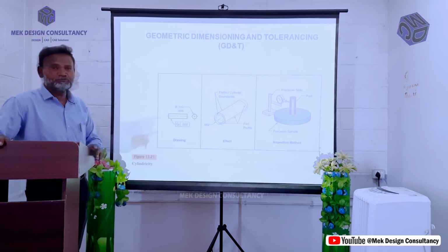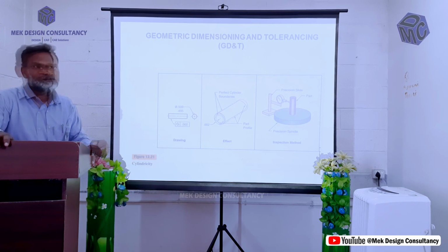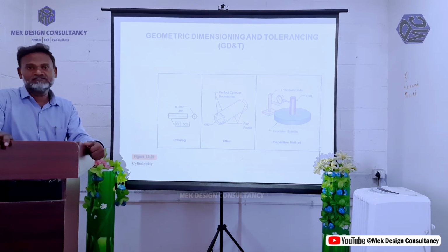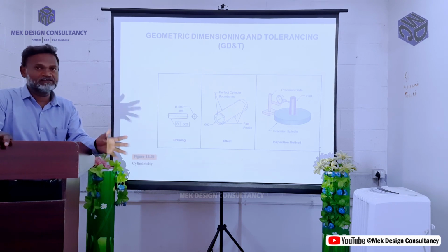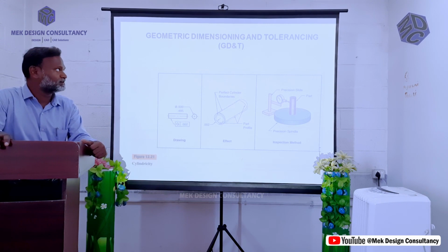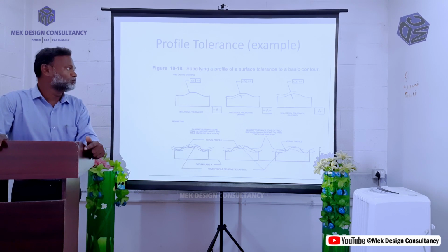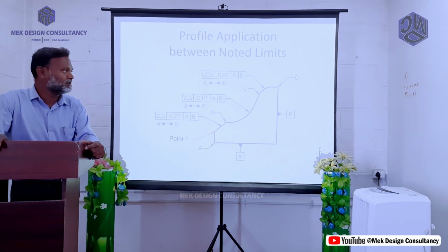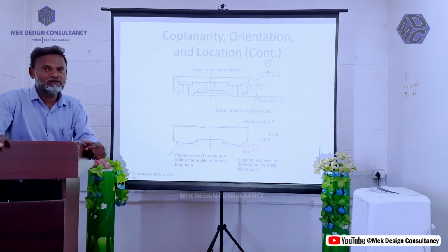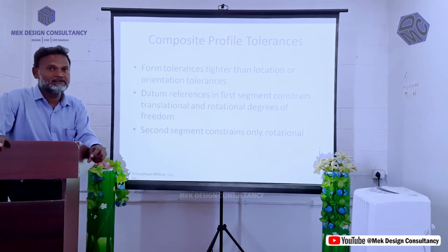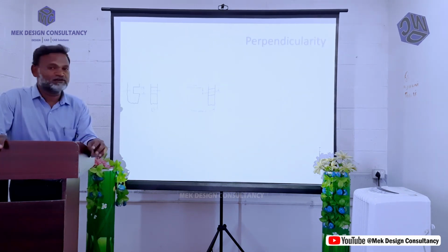After manufacturing, for the inspection method, we have to use a flat plate to hold the component to check within the limited dimension by using a dial gauge. After completion of that, we have to segregate whether the component is accepted or rejected. There are many symbols and representations to determine the tolerances using GD&T symbols. As per the tolerance, make the drawing and go for manufacturing, then finally test the component. Then finally you will get the best product, meeting the market availability.